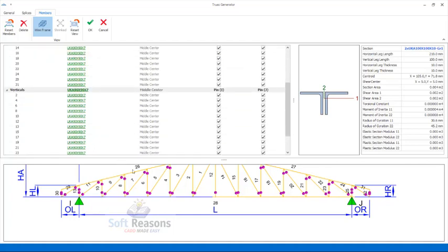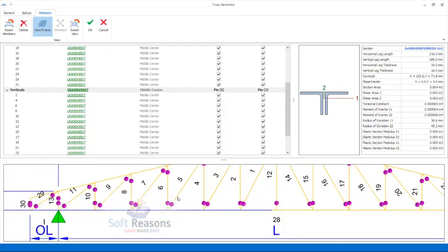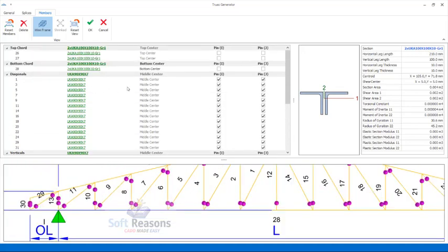Okay, so in this kind of roofing, the steel members are supposed to be single angle and not double angle. So what you see here at default is a double angle, and then the section is 100 by 100 by 10. Okay, so this can be changed if you click on these provisions.